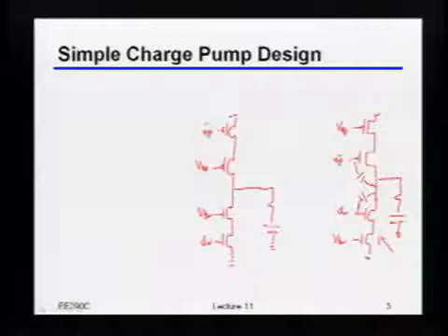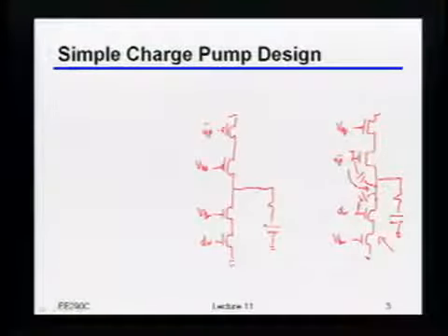Okay, so if I want everything relative to ground, out of either the PMOS device or the NMOS device, when it's off, which one is connected to VDD at its gate? Up bar. Yeah, up bar, right? So the PMOS device, when it's off, will be VDD at that gate. So what will happen is you'll just get some straight capacitive coupling directly to the output, right? Now, maybe that's not too bad. Maybe you can make that ratio sufficiently good, meaning that you can make the loop filter cap substantially larger than that coupling cap from the switch.